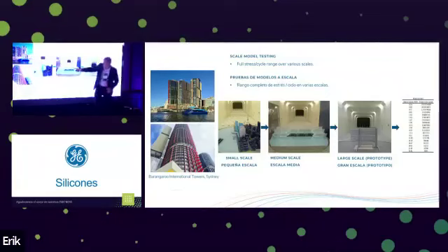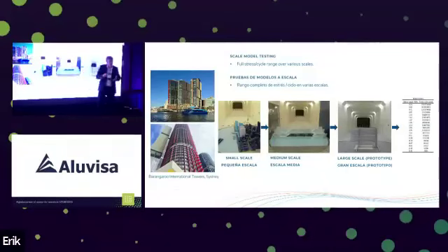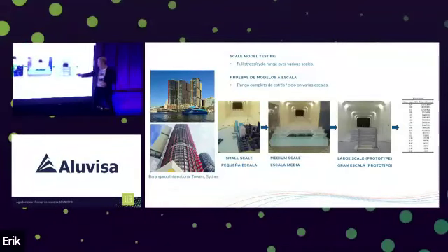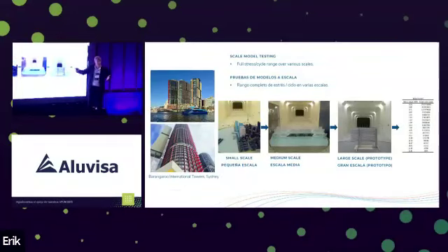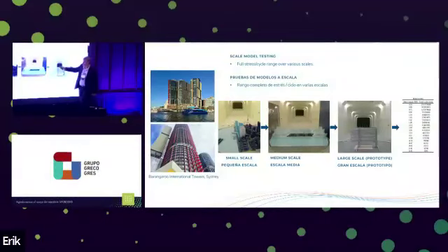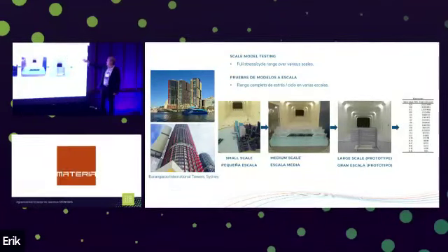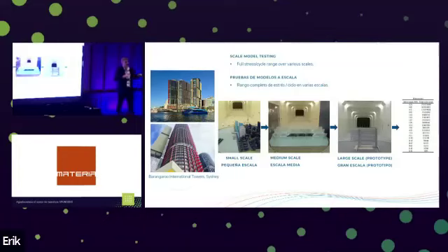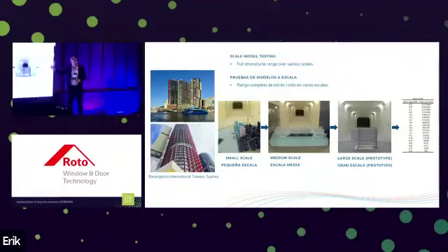The second model is an intermediate scale, where we're looking at the interference effects between adjacent fins. And the third test is on the prototype, the full scale, so we can actually calculate the drag coefficient. Now we can combine those 3 scales when we do that analytically post-test, and we end up with a stress range versus cycle count. Now this information can be fed to the facade engineer and fed into their finite element model, and they can then run the check on whether the fatigue life is going to be suitable for that particular installation.